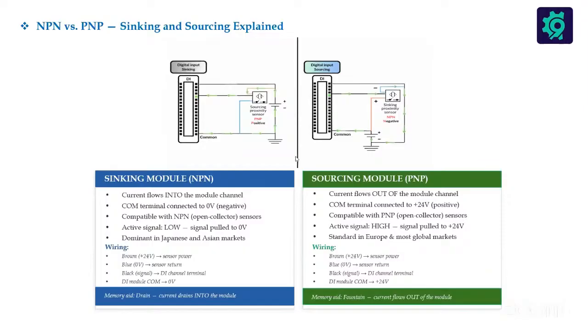So now the positive will enter into the PLC through that sensor, so it's going to be sinking into the PLC.